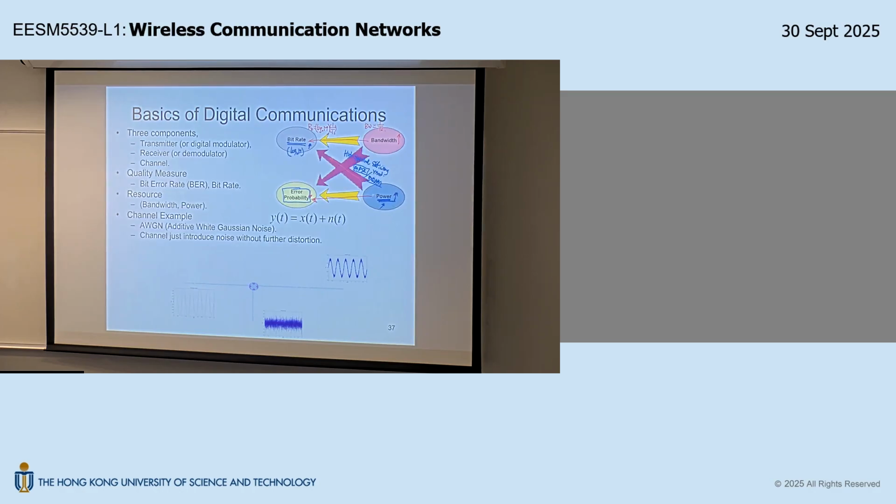Now, that's a little bit more elaboration. In practice, as I said, you have the MQAM and MPSK modulation family. You want to increase M so that your spectral efficiency is higher and higher, without paying the bandwidth cost, at the expense of extra power. But in practice, it depends on the system. Let me explain. The highest constellation I come across in practical design is like 4096 QAM. It's crazy, right? It's on a two-dimensional space. You squeeze 4,000 points on a two-dimensional lattice.